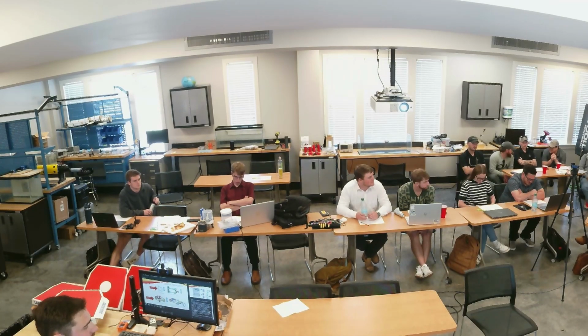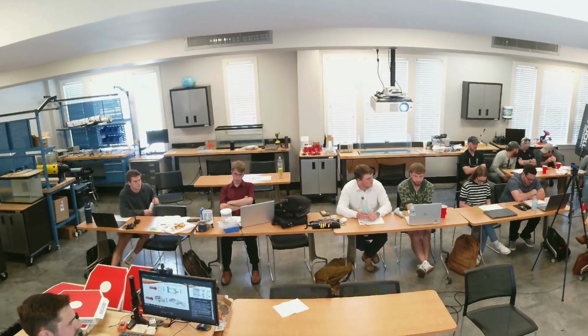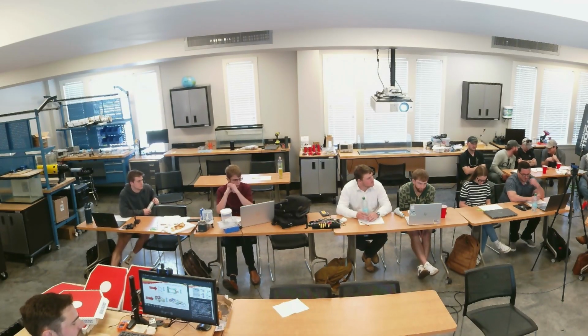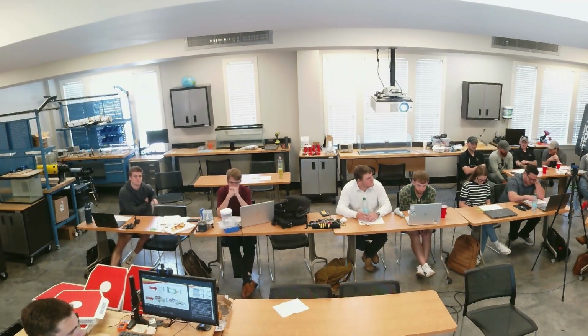So the systems they use in the RoboSub, they usually don't rely on just 4 propellers. Right? They have independent propellers for all the different uses. Yeah, 6 or 8. So they don't run into this issue where you lose all up and down motion with a 90 degree tilt. They have different systems, better decoupled than your system, because they have more actuators to decouple the different degrees of freedom.